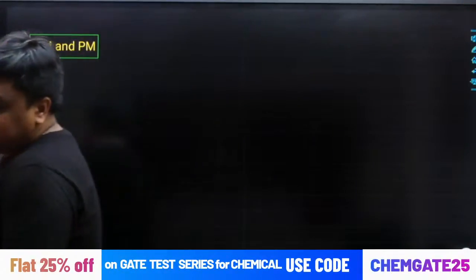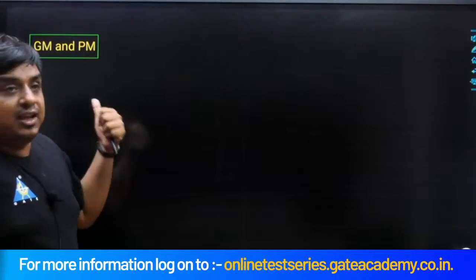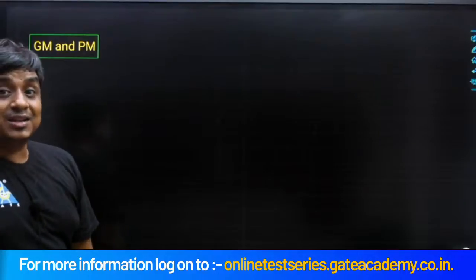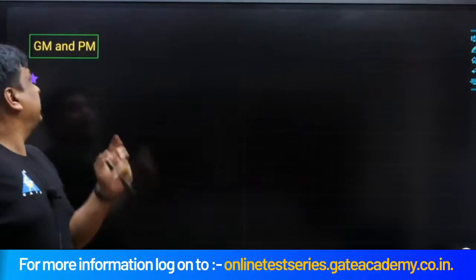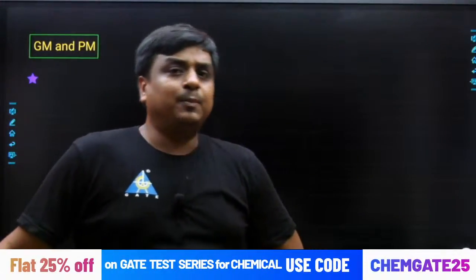Similarly, what does it mean by the phase margin? The margin in phase. Earlier we had the margin over the gain, and now we are talking about the margin in phase. One of the best things regarding gain margin and phase margin is that so far we were doing the stability analysis using the Routh-Hurwitz criterion, and with the help of root locus. There the relative stability was not known.